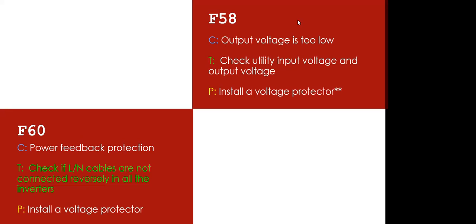If the phases are in sequence, it will show you that the voltage is in sequence. It will show each voltage from each phase. But if it is not in sequence, it will still indicate where the error is coming from. So this device will help when we are doing either a three-phase installation, or when we are paralleling two or three inverters together.